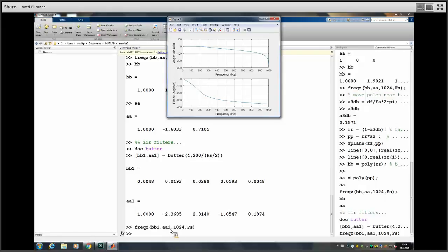Let me take a quick look at the help. Elliptic, elliptic, elliptic, yada yada yada. See also ellipord. Okay. For elliptic filter design, there is also ellipord, which basically calculates the minimum order of a digital or analog elliptic filter required to meet the set of filter design specifications.